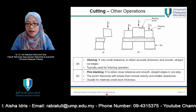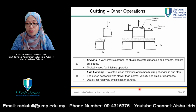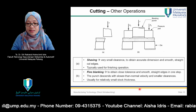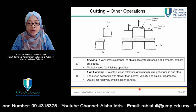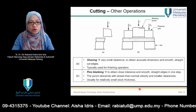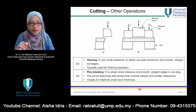And then fine blanking. This one is used to obtain close tolerance and smooth straight edges in one step. The punch descends with slower than normal velocity and smaller clearances, usually for relatively small stock thickness. Small stock thickness means a blank with a lower thickness value.